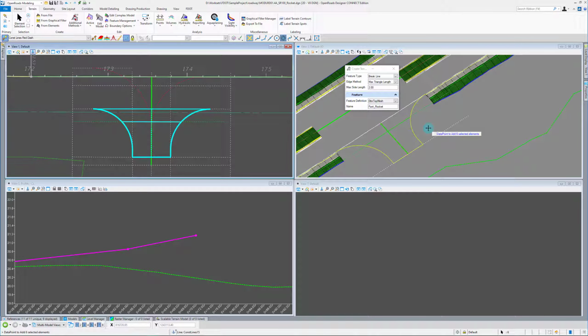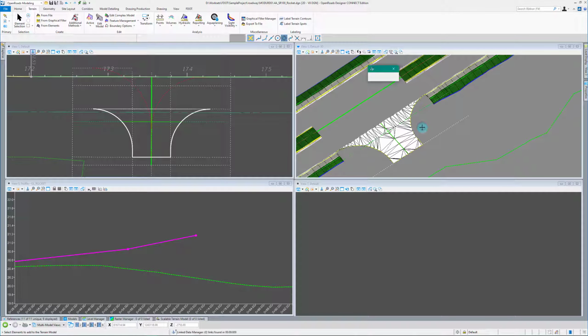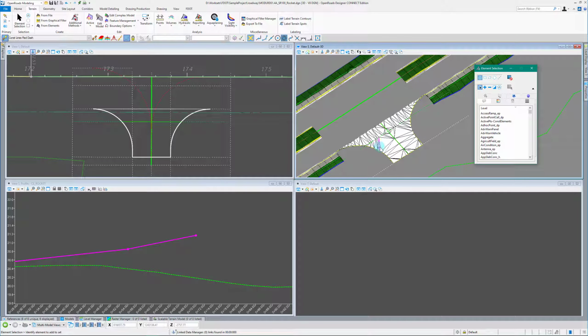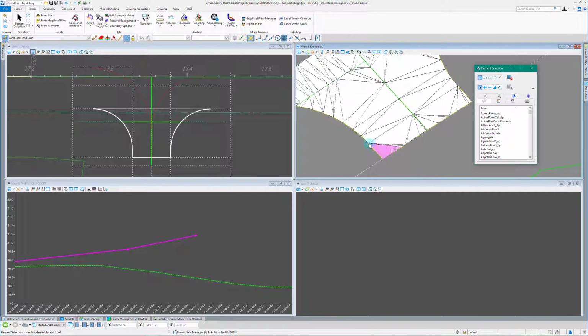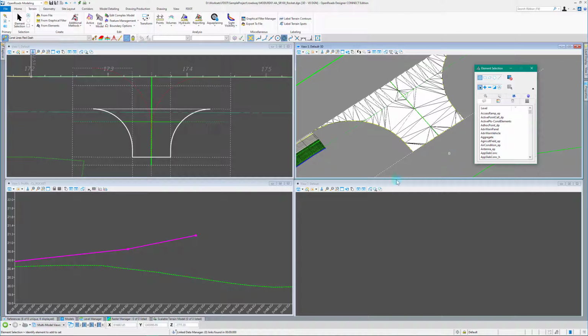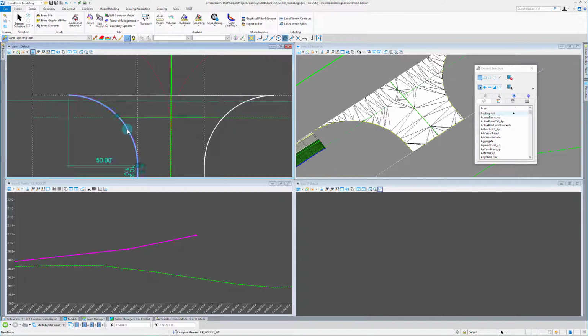So we're going to data point and just keep data pointing to get through all of these, and we have our terrain. So you can see there's a vertex about every 10 feet. Now that's okay for some of this stuff, but I find I like increasing the linear stroking on some of these lines, or decreasing it, I guess. Increasing the drop, decreasing the number.